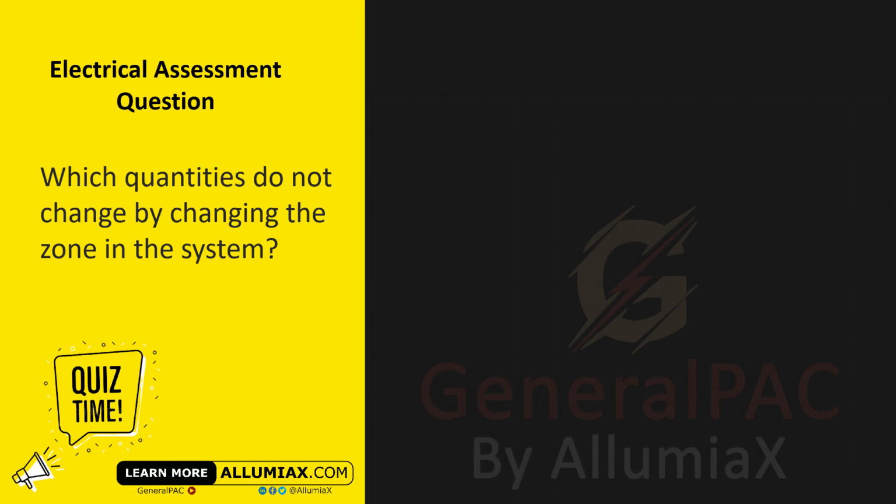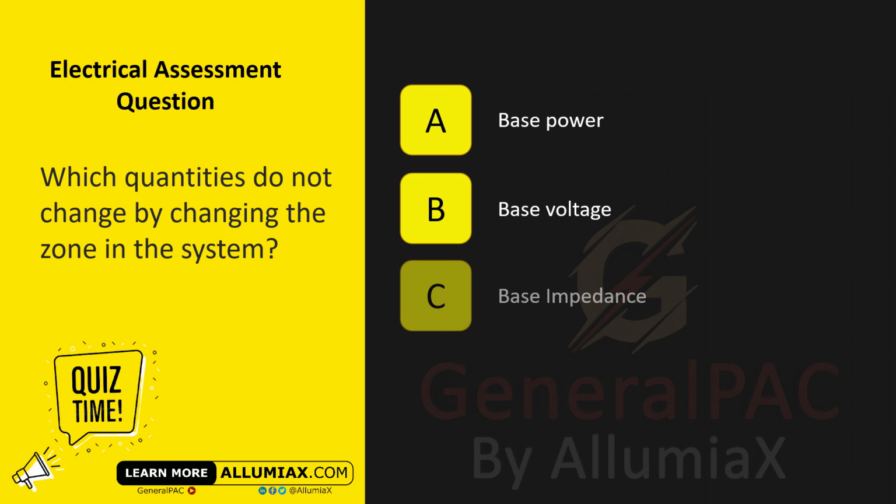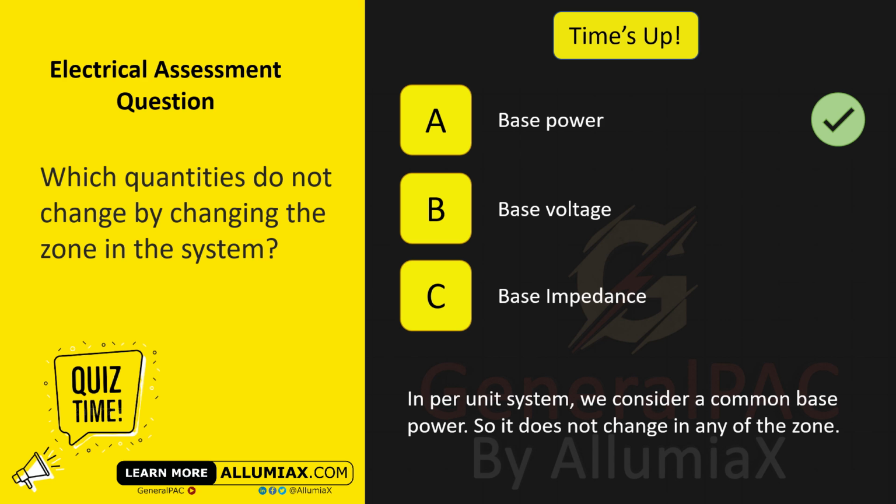Which quantities do not change by changing the zone in the system? A. Base power. B. Base voltage. C. Base impedance. Time's up. The answer is A. Base power. In per unit system, we consider a common base power, so it does not change in any of the zone.